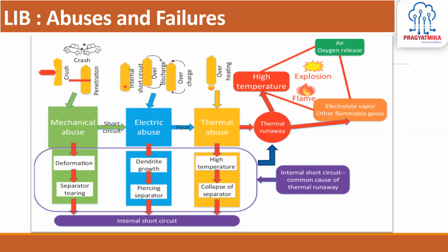Mechanically it could be abused, where crushing or penetration of your cell happens due to a vehicle crash. Maybe the placement of the battery pack is not good, so even if an accident occurs, the battery pack can get crushed. So there are deformations and tearing of the cell separator.